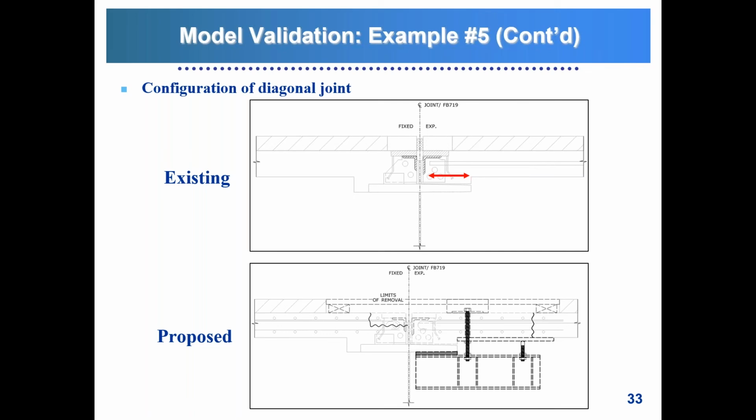The problem with that is that with time, not only did that floor beam begin to corrode because of leakage through the joint, but this side of the deck ended up hammering against the top flange and damaging the deck.